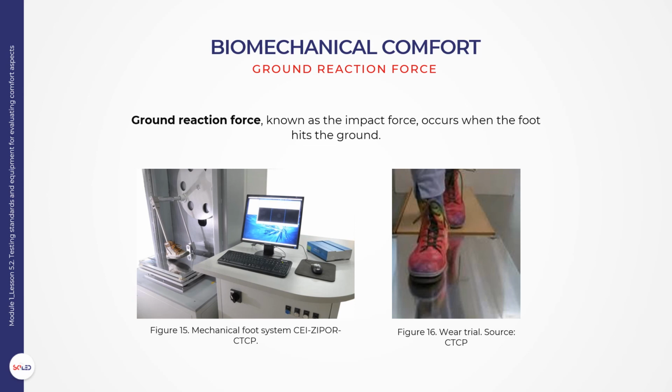The selection of a panel of individuals, which can involve more than one group, depending on the aim of the study. Each individual wears the footwear for a period to allow the acclimatization of the foot to the footwear. The individuals are asked to walk in a natural and comfortable way in a defined path that integrates the force platform. The results are analyzed and interpreted, with regard to vertical ground reaction force, anterior-posterior ground reaction force, and medial-lateral ground reaction force.